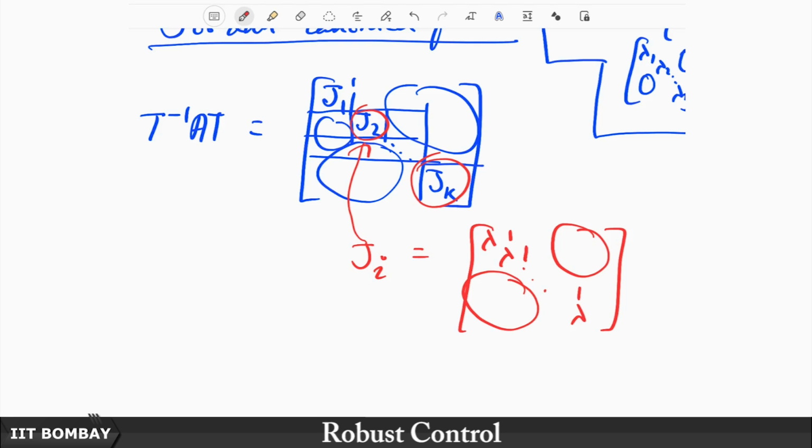And what is even more startling and amazing is that even if you cannot diagonalize a matrix, there will always exist a similarity transformation that allows you to get to the Jordan canonical form. It holds for every square matrix and therefore for every linear operator, or its matrix representation, and that is very good news for us. For us means those who are interested in studying these linear maps, these dynamical systems represented in the state space form given by x dot is equal to Ax plus Bu.